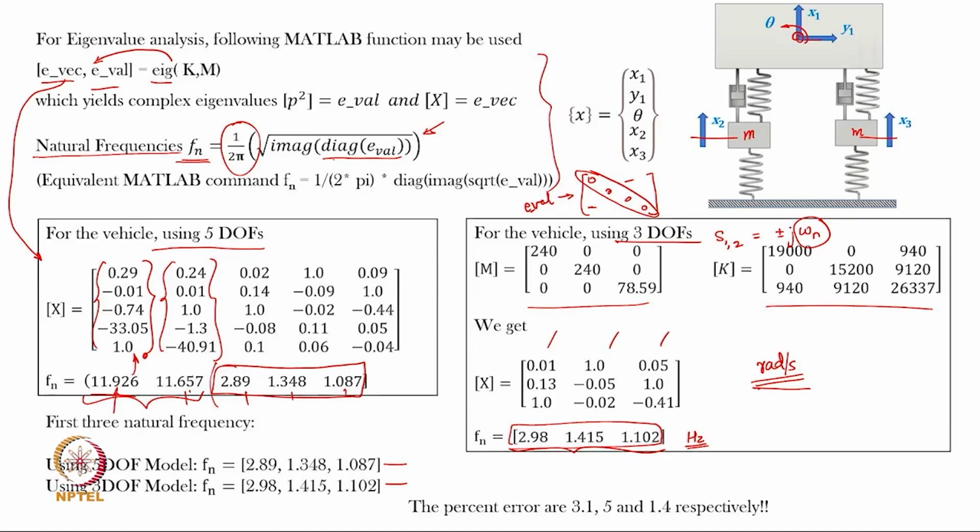And usually we are more concerned about the initial few eigenvalues or natural frequencies. The higher eigenvalues are not always essential to find. Now, we have discussed this in terms of that winch problem, where the higher natural frequency is far apart from the normal lower natural frequency, and so it depends upon what frequencies are excited in this system.